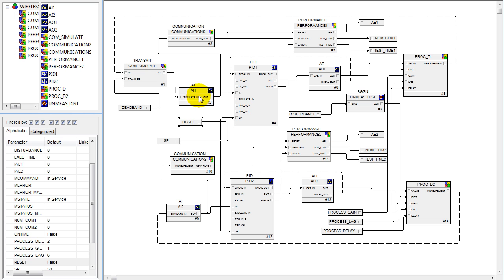The module we'll be using is shown here in the upper part. We'll be simulating wireless communication of the temperature measurement. PID Plus will be used, and that will be adjusting the output. We'll be comparing it to conventional input, PID, and output. To allow performance to be compared, we'll be simulating two heaters. These simulations are identical, each having the same gain, dead time, and time constant.